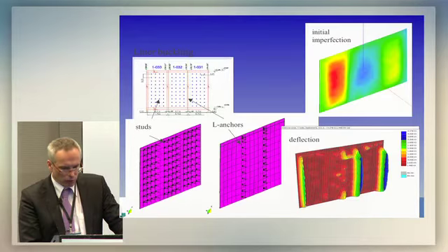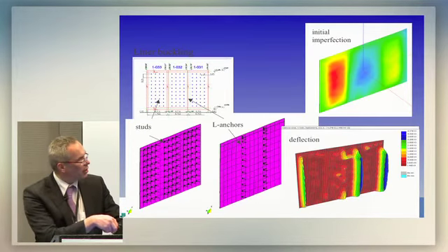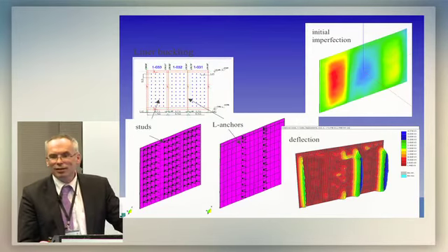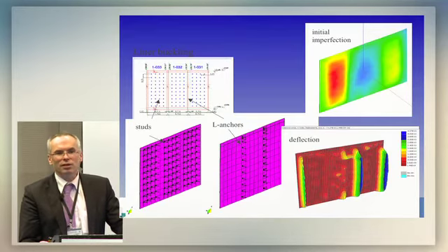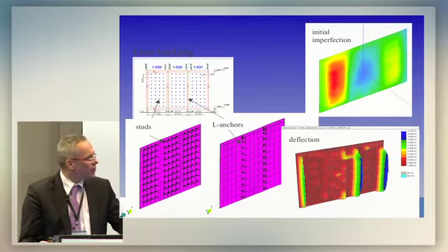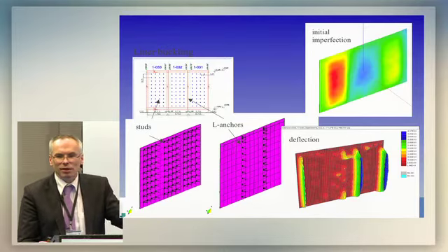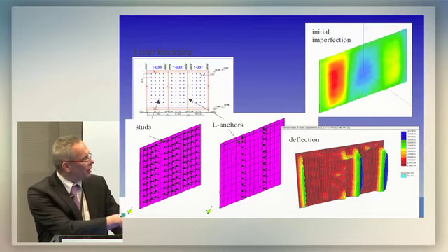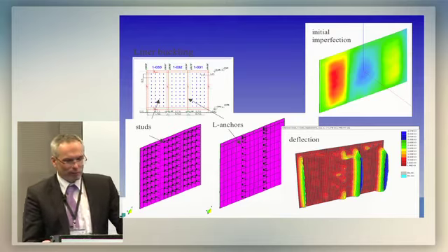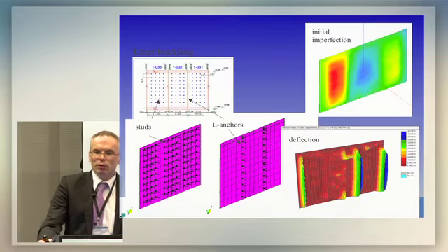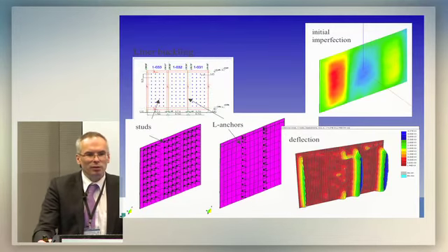This is an example of the buckling of the liner. That's because one of the important design criteria in the containments is that the strain in the liner should not exceed certain values. The problem is that such an evaluation is, I would say, old-fashioned, because the strains could be very large if you think about some details, such as the connection of the liner to these anchorages. So when checking by nonlinear analysis, the strains will be whatever value you want, depending on the finite element size that you select.